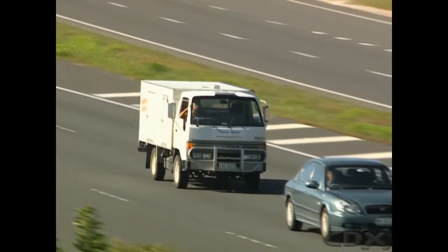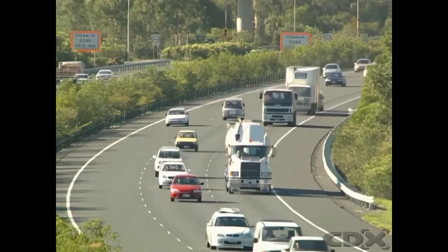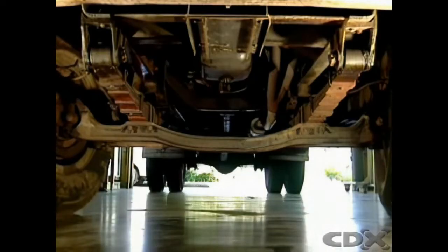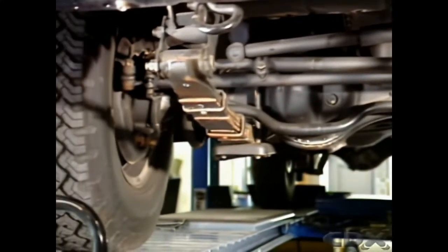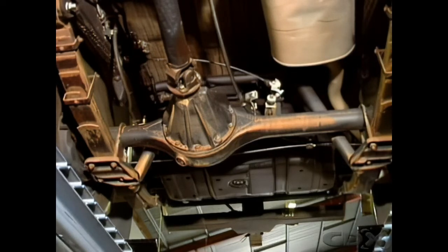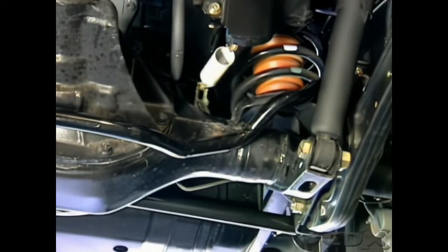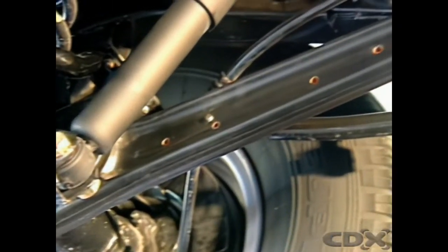Passenger cars no longer use beam axle front suspension, but it is still common on heavy commercial vehicles and some four-wheel drives. Trucks use an I-beam, in most cases located by leaf springs. Four-wheel drives with rigid axles may use leaf springs for front and rear suspension. Coil springs may also be used for front and rear, and as with other beam axle designs, a lateral rod and control arms must be used for location.